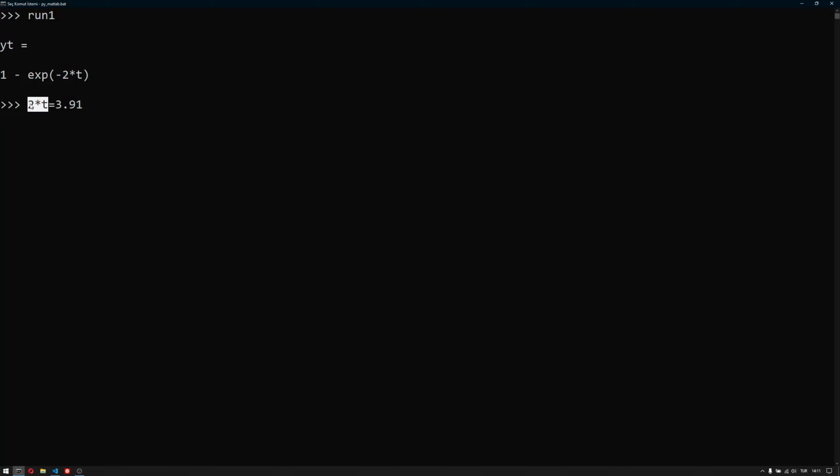So if I have 2t, it would be half the time. So it would be twice faster. So it means that divided by 2 should be the time instant that I should be looking for. So it will take approximately 2 seconds, but let's say 1.96 seconds to settle down for this system.